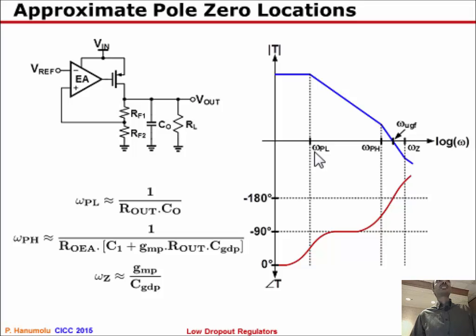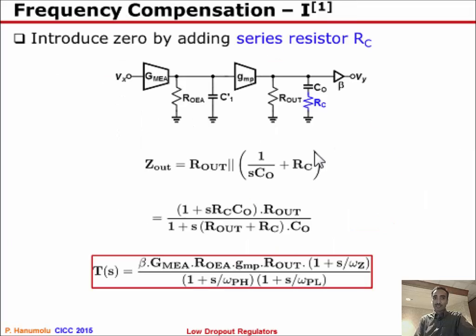And when we do this, these compensation schemes must be robust to variations in load current, because these LDOs could be used across a very wide range of load currents. And for LDOs with an off-chip capacitor, these things should also work with varying output capacitances. Right? So these are the additional things that one will have to keep in mind.